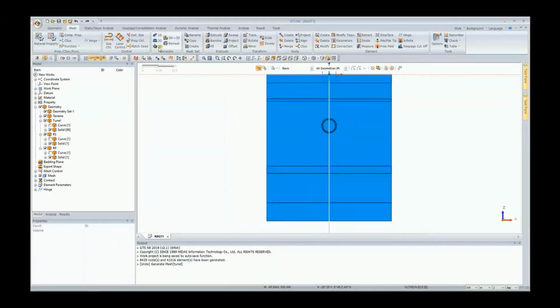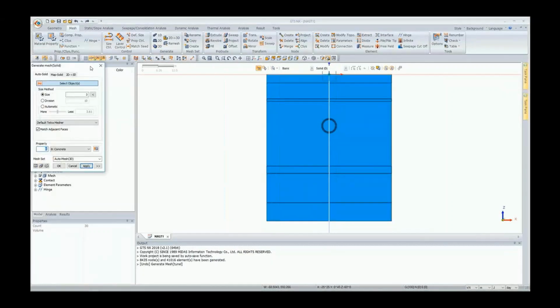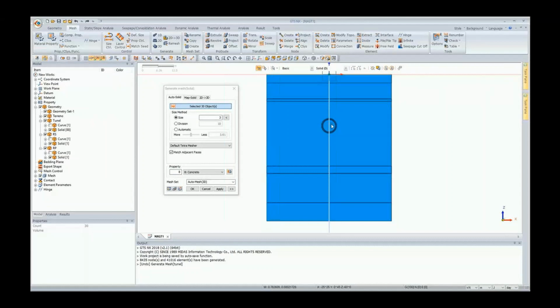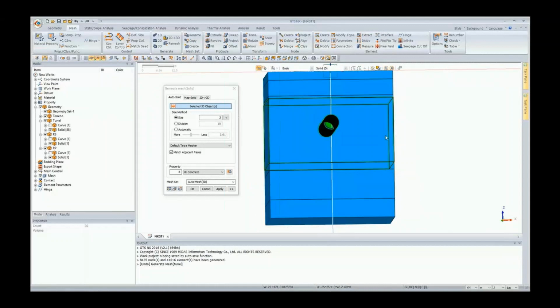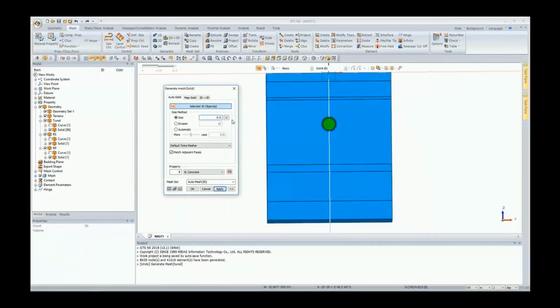And it's a good tip to start from in to out, in which the outwards would be the larger meshes. So here, I'm going to first start with the tunnel, the innermost part, and I drew a little line, again with the intersect filter to select them all, and now I give it a size. It's going to be 0.5 meter, and I'm going to select either tetra or hybrid mesh. Hybrid is a combination of elements with cube and pyramid, so let's do the hybrid. And since this tunnel is in the layer FAS2, this is the material I'm going to assign to it.